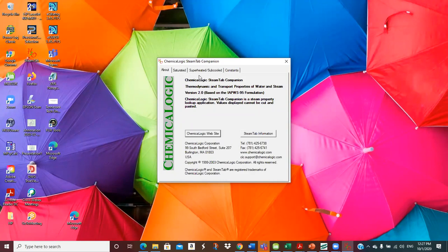So I can divide this by 0.8 because I don't have to get this gas out of this water heater or liquid heater, whatever it is. So divided by 0.8, now that's 2.789 million BTUs an hour.